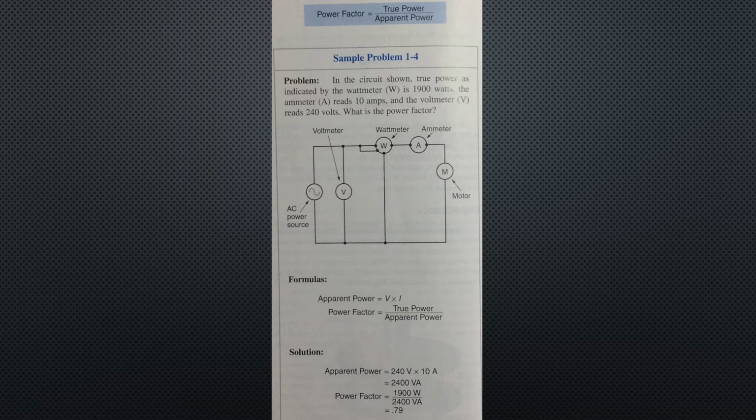This still holds true for DC circuits as well as AC circuits in which the current and voltage are in phase and all energy from the source is fed into the external circuits. However, when the current and voltage are out of phase, which is quite often the case with practical AC circuits, some energy is fed back from the source to the external circuit.